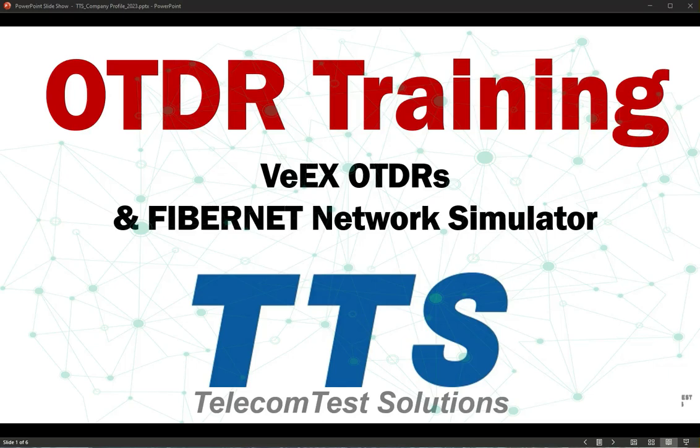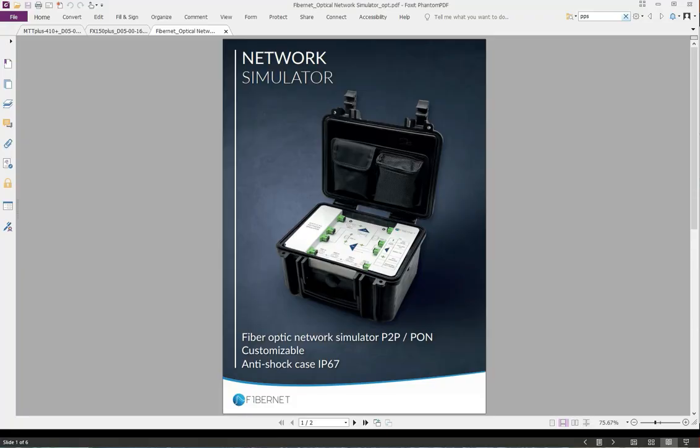Hi everyone, in this video we will be doing an OTDR training using the VeEX OTDRs and the FiberNet network simulator. To give you an idea about these tools that we'll be using for the training, first of all, that's the network simulator box, which has got a fiber setup inside, like point-to-point and a PON network inside. We'll have a look through the OTDR how this network looks like from inside, the different losses, and the arrangement